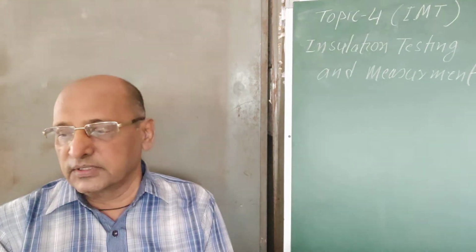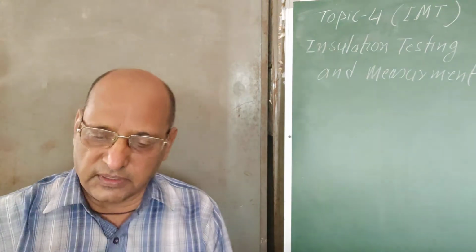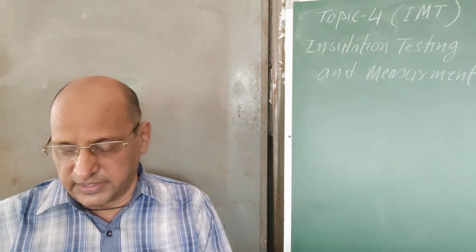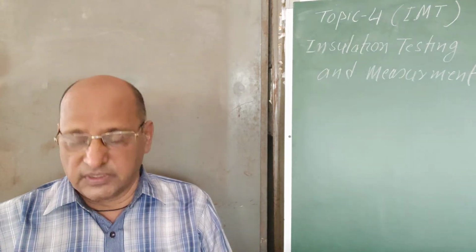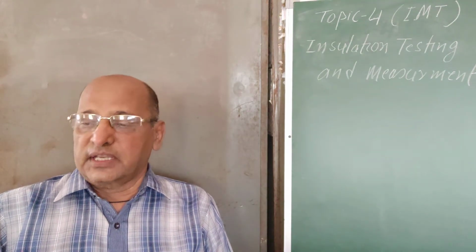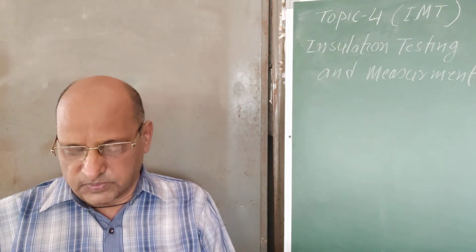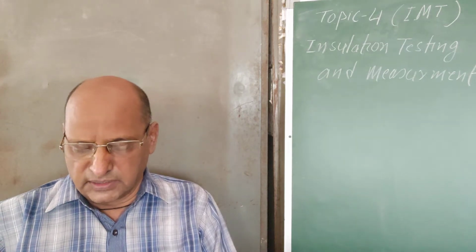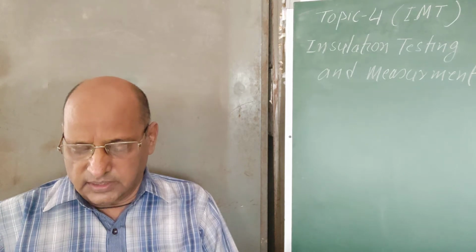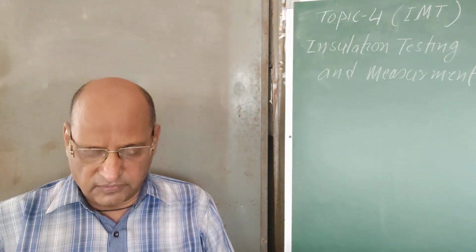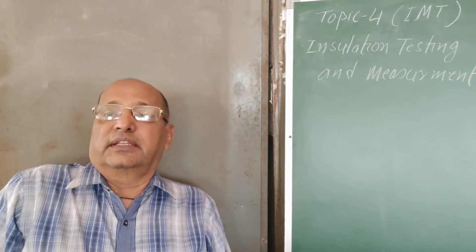So first of all, we discuss why insulation is required. What is the definition of insulation? Insulation is a layer provided over the conductor with the help of insulating material, which has different classes from A to E. The class is chosen according to the use and the working temperature of the winding or insulating material.